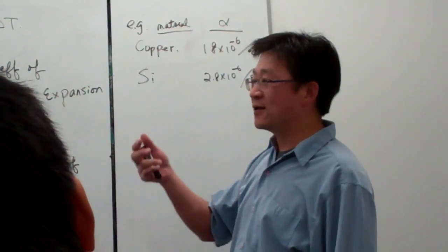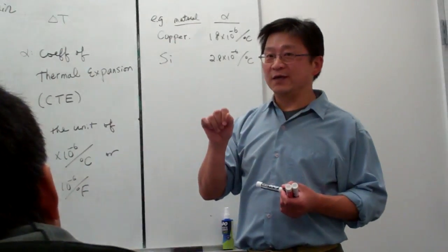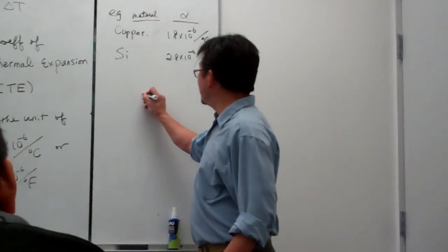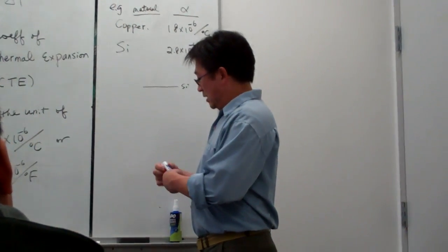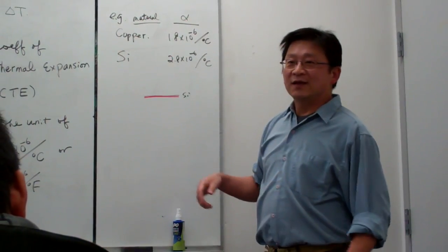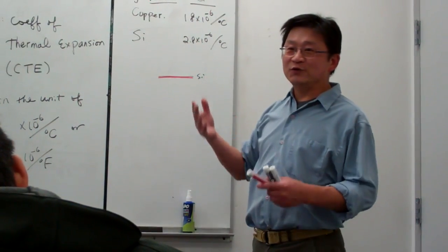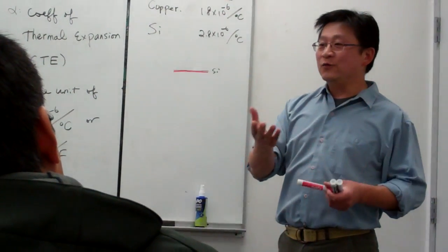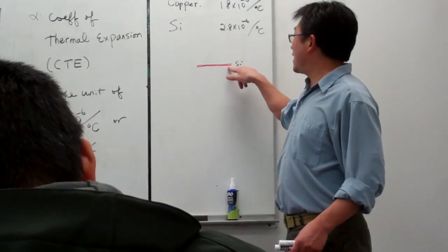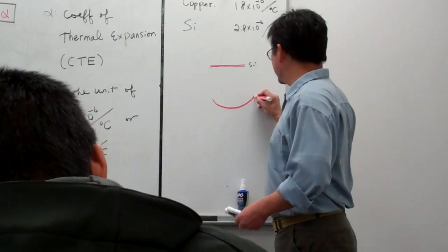And they use a lot of these two materials, so I remember the two numbers. You can see, for that kind of cell phone, in a single black chip, there's a very tiny, very thin, but there's a lot of components there. Those components are basically made of the two materials. And then what happened? If this would be the silicon, and this would be, say, copper, they kind of grew together in concept. You can see that is a huge thermal difference, right? So once the temperature heated up, for example, when you use it and you feel warm on your cell phone, copper tries to expand much more than silicon. So basically, these both things will become like this.